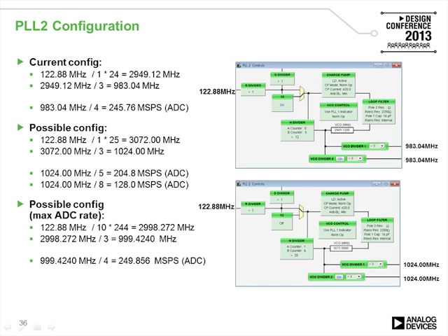If you want integer functionality to get like 128.000 megasamples per second on the ADC, you could use 3072 megahertz in your internal PLL2, which then can divide by 8 to get an even frequency. If you want to increase things to get exactly 250, the closest you can get is 249.856. It all depends on how you set these clocks up, and they are fairly flexible.